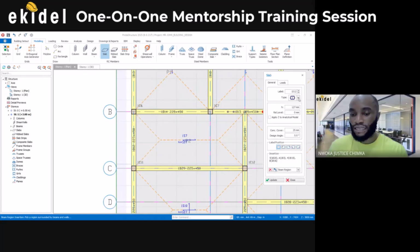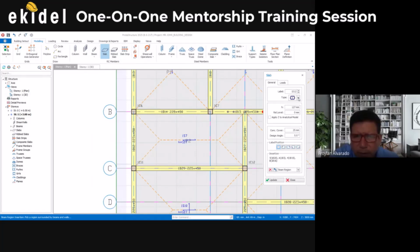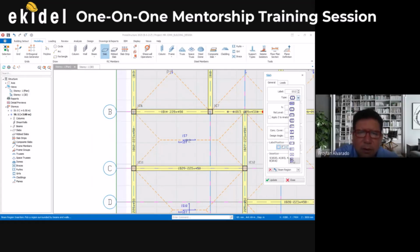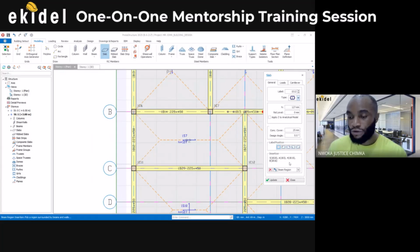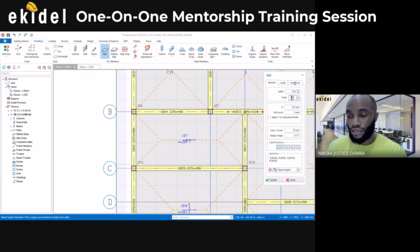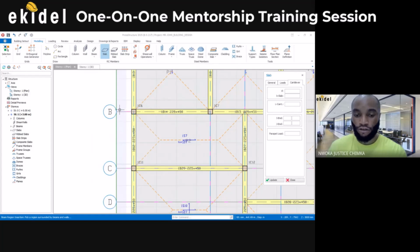And then you see it says type here. You click on type 12 here, which is this last one, Cantilever. I'll click on it, and then you see that you have a new tab here that says cantilever. Now click on this tab. Before this, you must have known your cantilever length. At what length is it going?